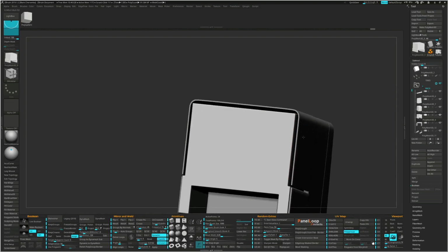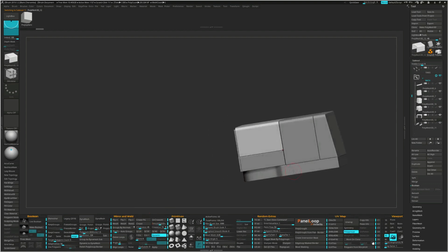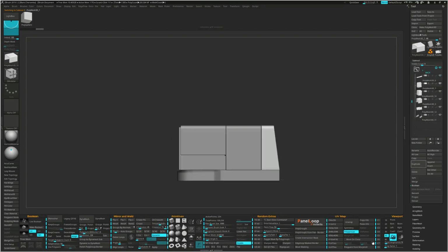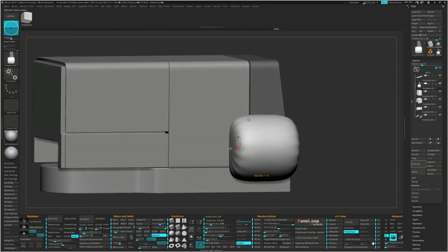There are a few ways to create beveled metal plates. The method I prefer is with a cylinder. Select the rear by Alt-clicking on it and then mask it. Turn on the gizmo and bring in a cylinder. Adjust the cylinder H divides to 32, split the mask points. Rotate and scale it into place.